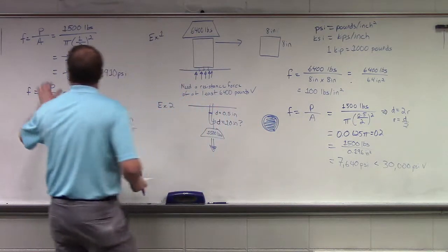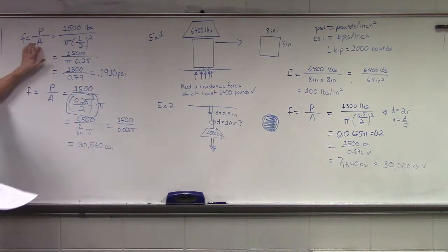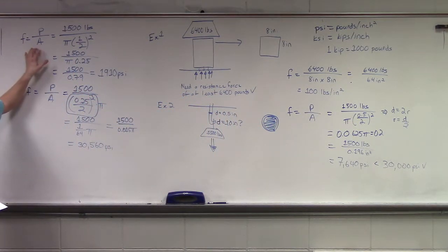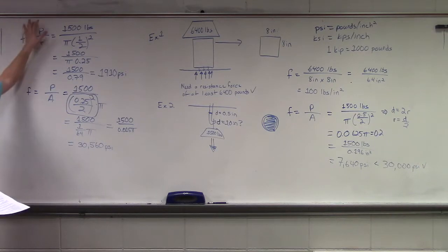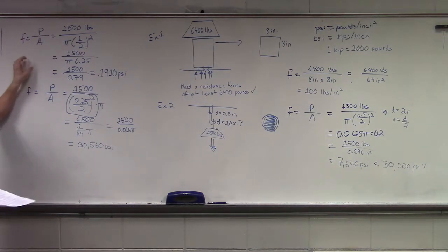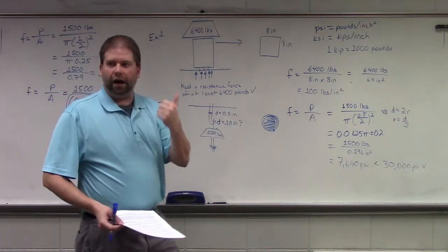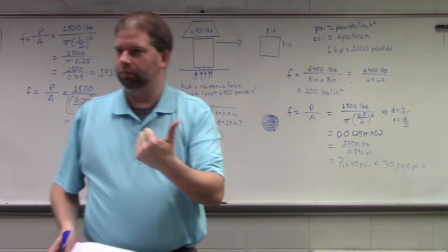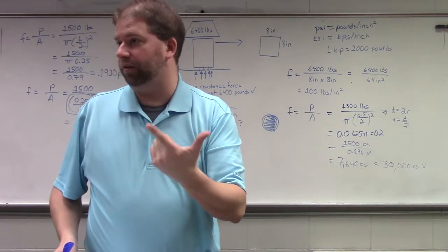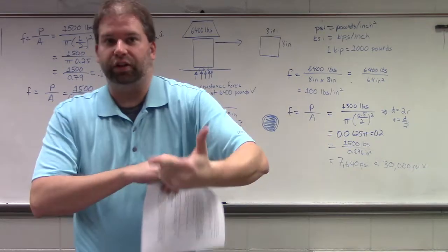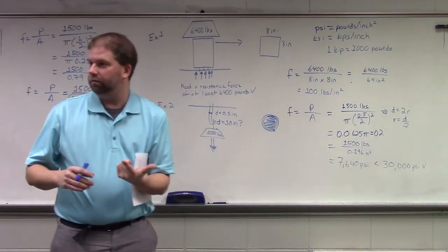So, what Rush was asking is, so far we've just looked at F equals P over A, right? But just as with anything else, we can manipulate this equation to solve for whichever of these factors we want, right? We can say, okay, I know the allowable stress of my material. I know the size of the material that has been specified by the designer.